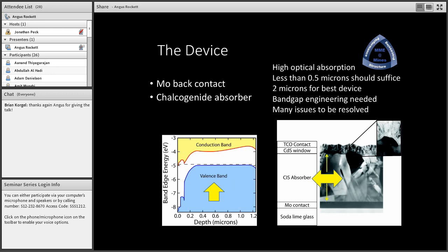and that's something that requires research. The devices pretty much always use some sort of bandgap engineering, usually increasing the bandgap toward the rear of the device. That provides an effective electron mirror because these absorber materials are p-type. The minority carriers are electrons. You try to collect them to the front of the device, which means that you're trying to keep them out of the molybdenum back contact, and for that you usually increase the energy gap in the material, typically by adding gallium, but there are other ways to do that.